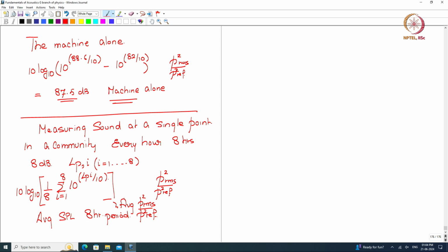There is a lot more to be said. We will look at the frequency content. This RMS value collapses all the frequency content. You could have the same RMS value for a high frequency signal or for a low frequency signal. So that frequency information is washed out. We will bring in how to account for frequency content in the next few classes. Thank you.